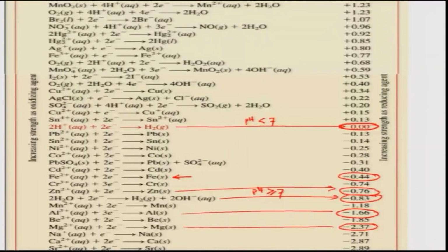You might have come across that magnesium is a very, very popular sacrificial anode. Even zinc is also used as a very popular sacrificial anode. Aluminum is a problem, though it can be used if we maintain the active nature of it.